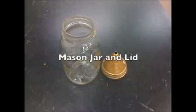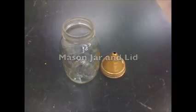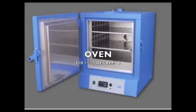To perform the specific gravity test, we will need a mason jar and lid, a balance. For AASHTO, this balance shall meet classification M231 Class G2, while for ASTM it must be accurate to 0.1 gram or 0.1% of the sample mass. And finally, an oven with a range of 110 degrees plus or minus 5 degrees Celsius.